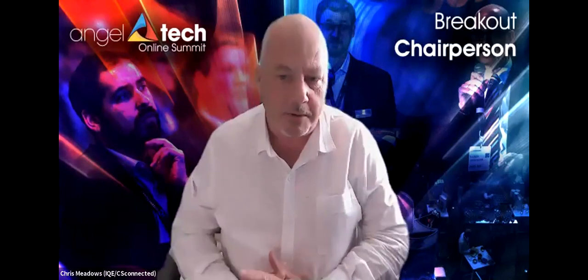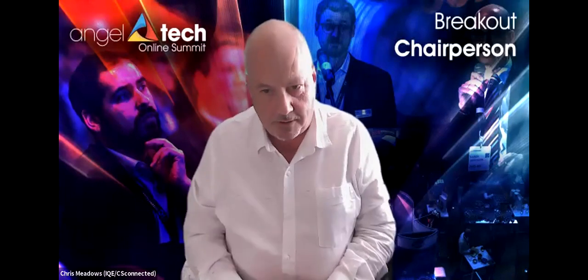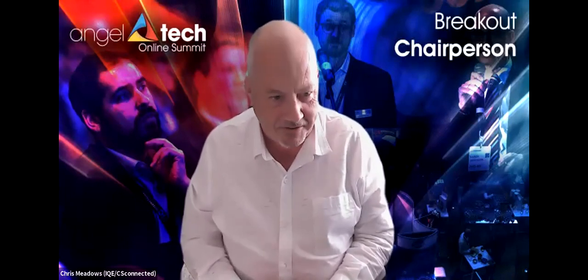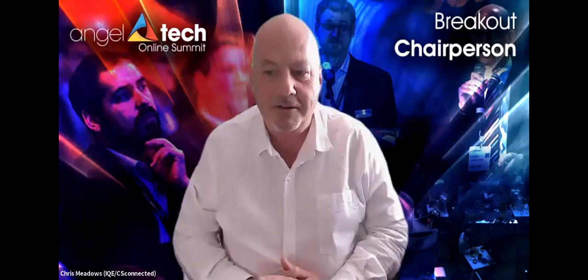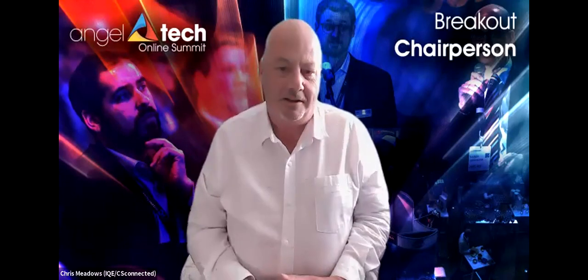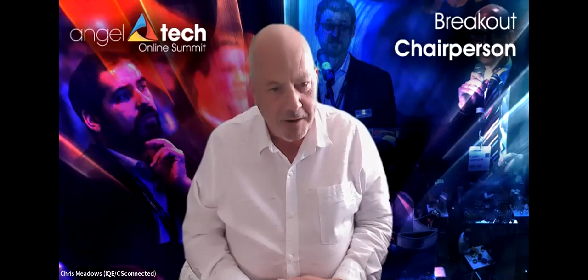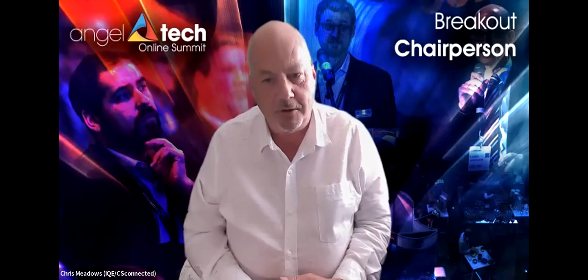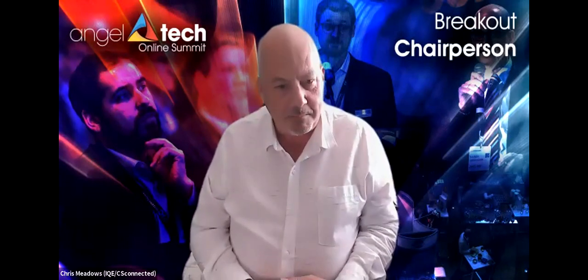It's Thomas Ehrman, Director of Business Development at EVG. The title is Compound Semiconductor Integration, Wafer Bonding Towards New Dimensions. Joining different semiconductor materials can be challenging due to mismatched material properties, such as coefficient of thermal expansion or lattice structure. Wafer bonding has proven to be a viable way to combine various materials by using interlayers like polymers or metals, as well as by direct bonding.